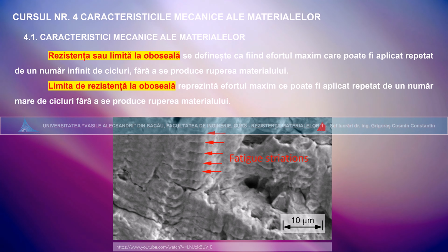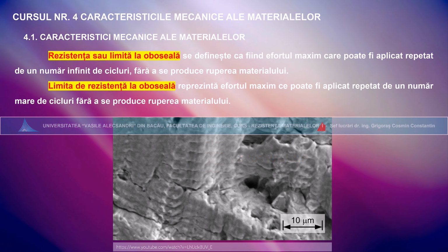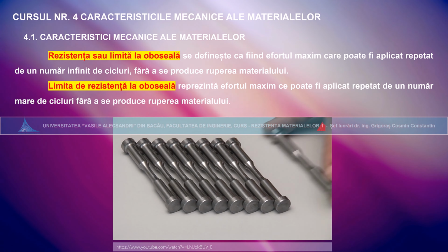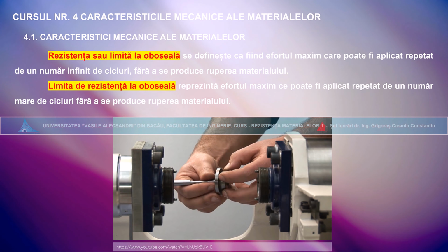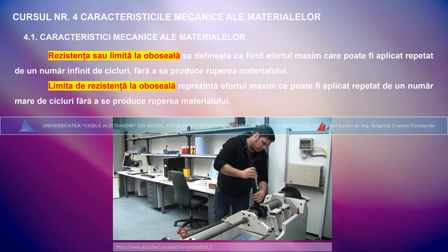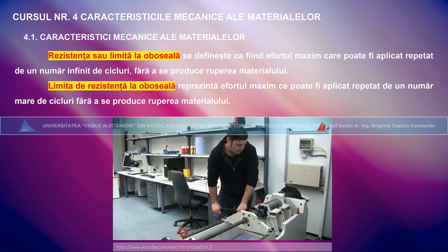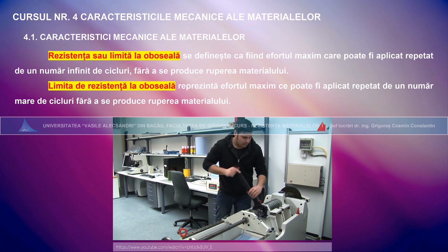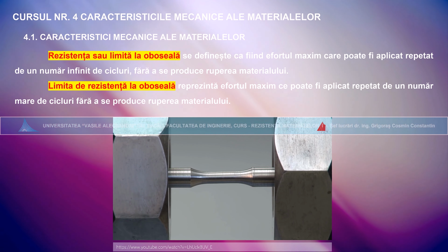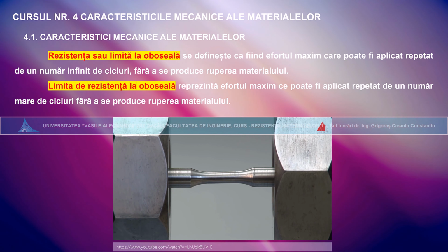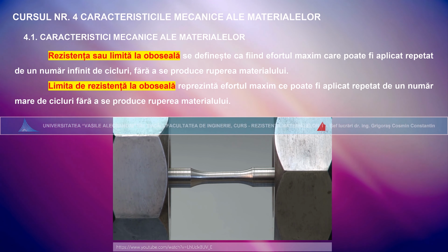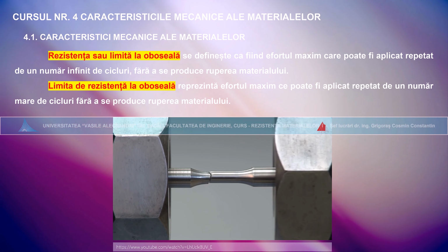Of course, now we want to know how many load cycles this material can endure with other loads. For this purpose, the material tester picks the next specimen from his supply and installs it into the fatigue testing machine. He chooses a higher alternating load for the second specimen, a tensile force of 7.5 kN and a compressive force of 7.5 kN. Under the increased load, the specimen is only able to withstand 43,600 cycles to failure.